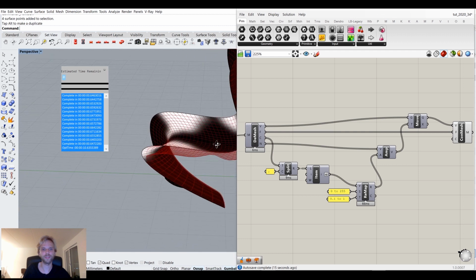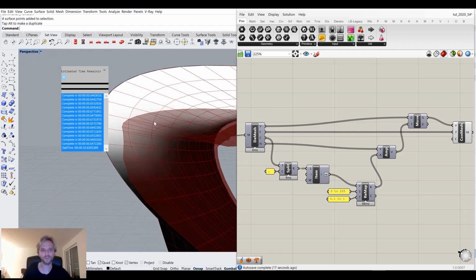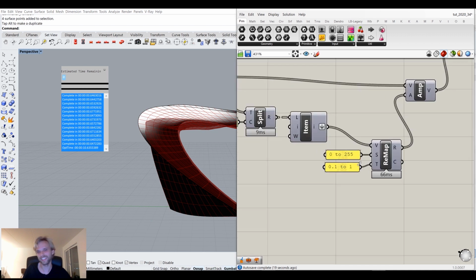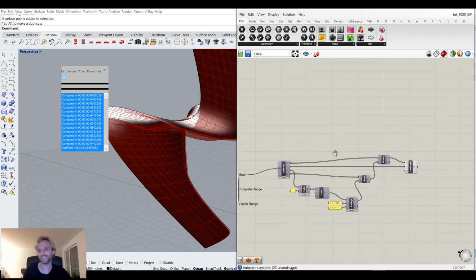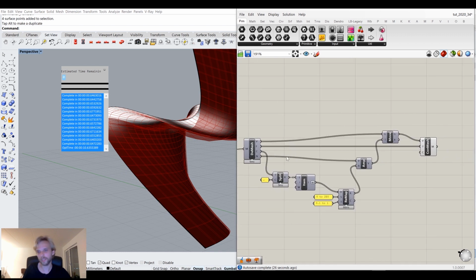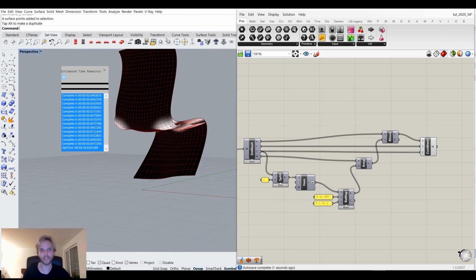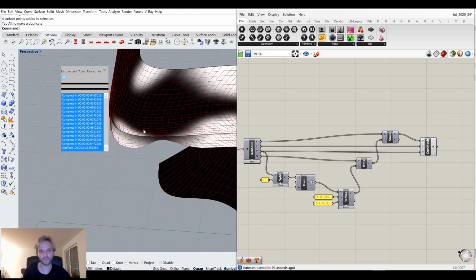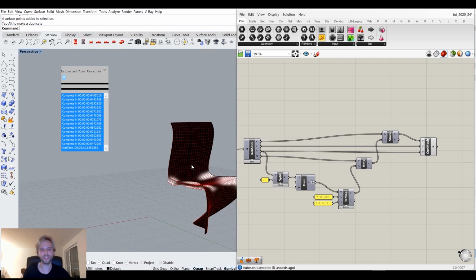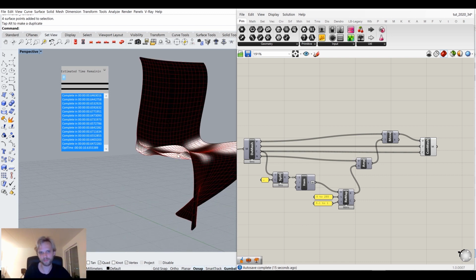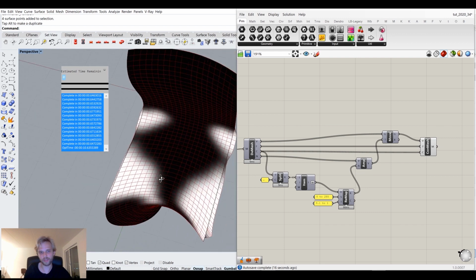And it doesn't look that great, I know, but yeah, what can you do? And this is too wide of a bend. That I also know. By the way, if you want to color them, you can. You just connect color to color information, and now the backside is going to be colored as well. And all you need to do to kind of close it off is just bake it out and loft between the two meshes, and it's just going to be lofted. I will not be doing that for you. You can do that on your own.